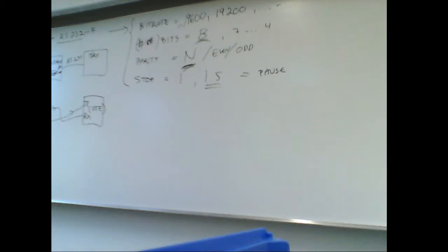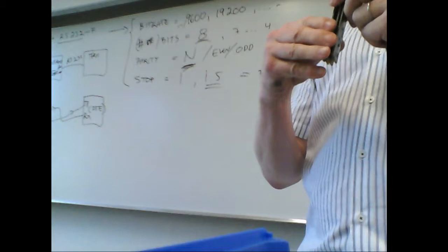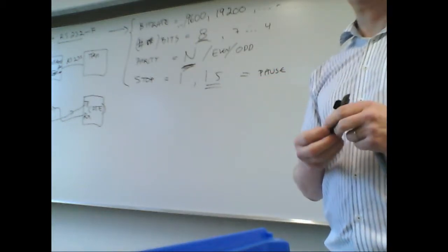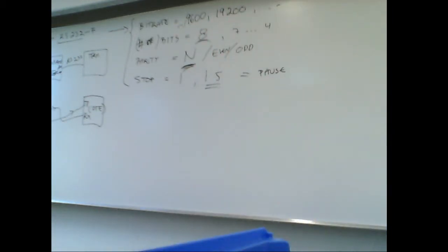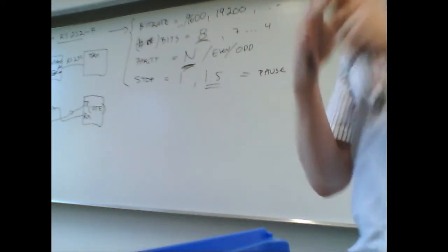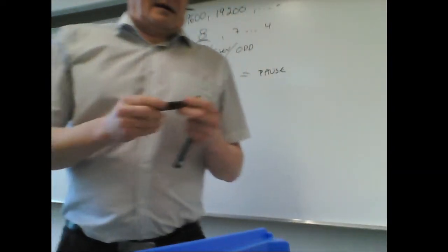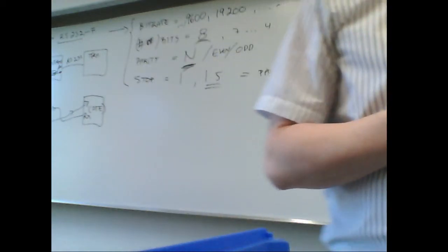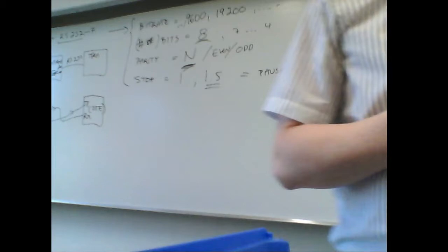This one here actually is the PSoC 5 development board, but it also has a serial to USB device inside of it. So you can use this one for debugging even with lower voltages than 5 volts. So you can run a 3 volt system and use this one for transmission between computer and your device.